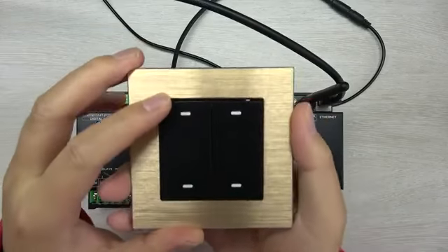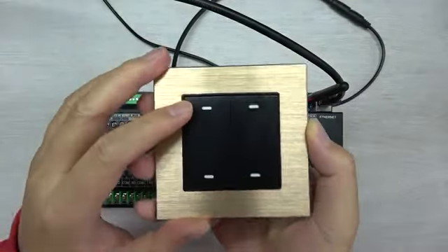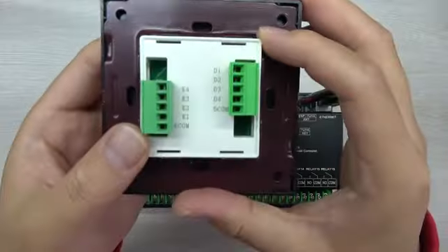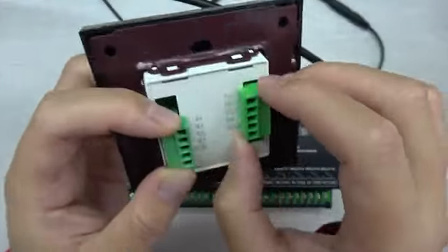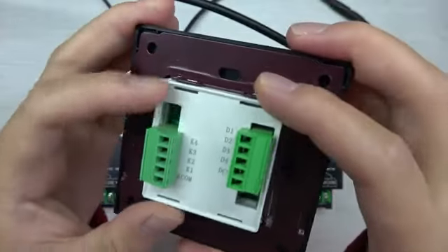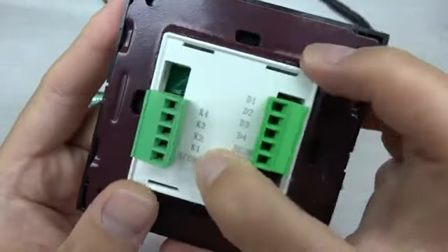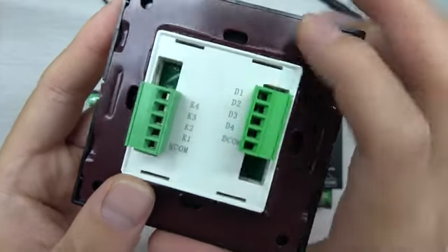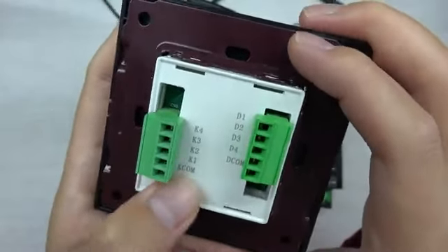And you can see this is a switch, this is a foreground. The switch also has different colors, 1, 2, 3, 4. And you will see at the back, this is for LED feedback. We don't introduce this firstly. We just want the first training simplest. So you will see this has a key 1, key 2, key 3, key 4. And this key COM, that means common and ground, connect with ground.